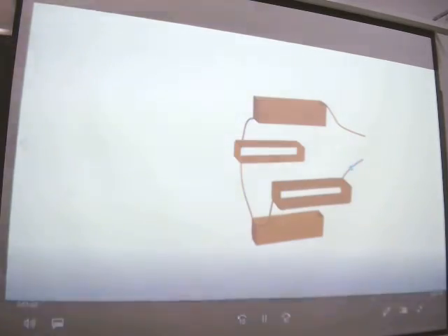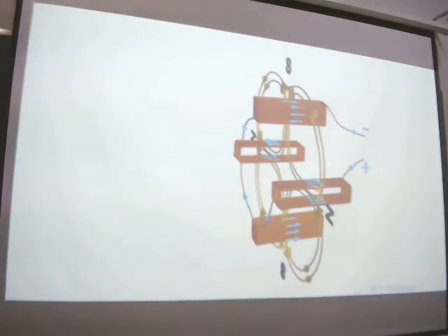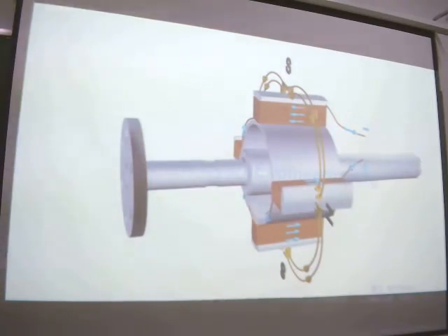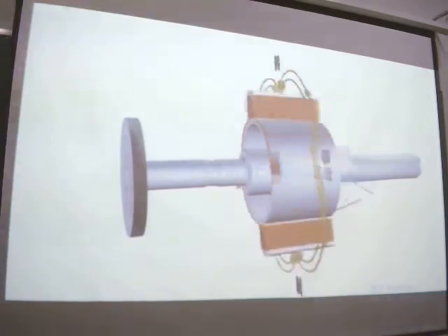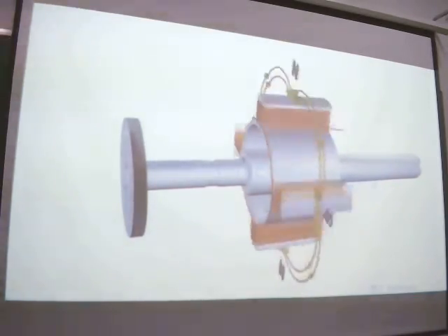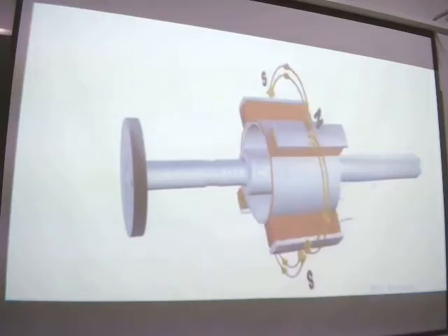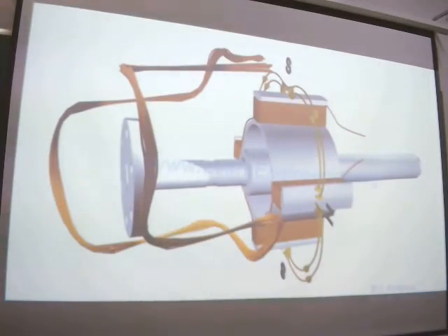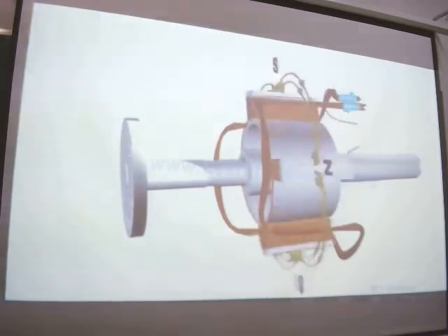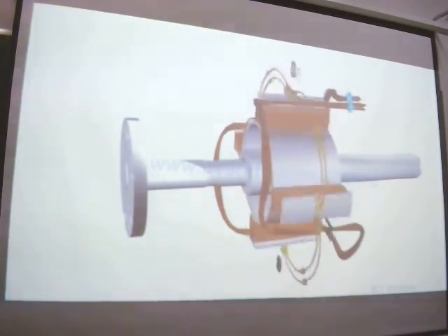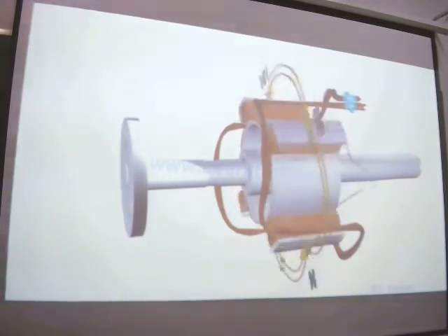Rotor coils are excited with a DC power source. Magnetic field produced around it would be as shown. The rotor is made to rotate by a prime mover. This makes the rotor flux also rotate along with it at the same speed. Such revolving magnetic flux now intersects the armature coil, which is fitted around the rotor. This will generate an alternating EMF across the winding.